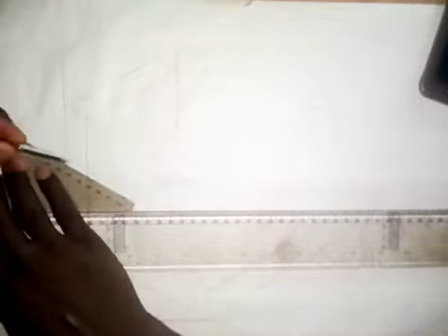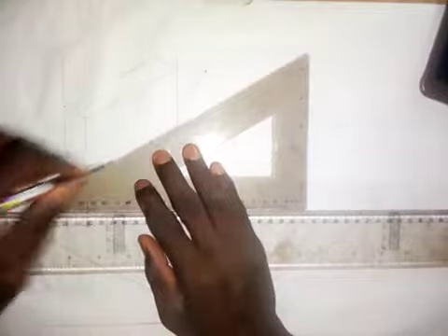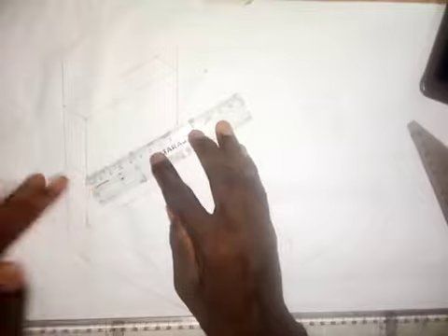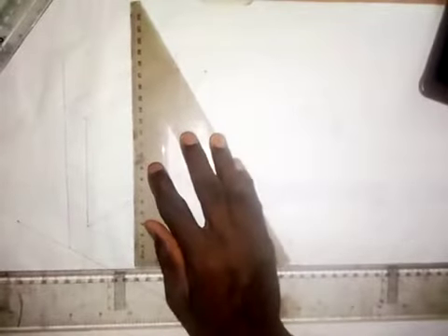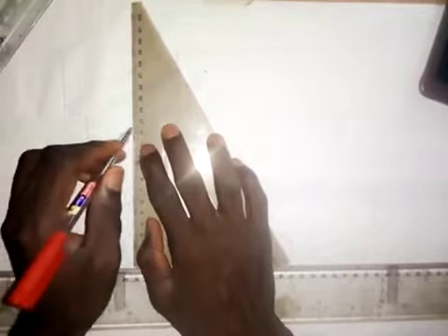So all I need to do here is to transfer this point. So I transfer it here like this, and then I will take it. Okay, that's almost at the same point. So I'll take it to this side. All right, so we have that. Then this 90, I'll divide it into 2. That is 45 millimeters. So I will draw a vertical center line on this face here. That line is supposed to be a center line.